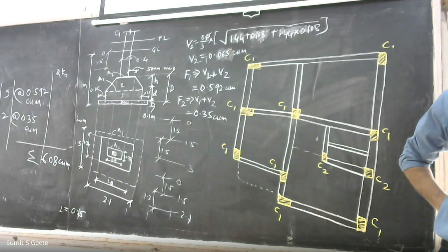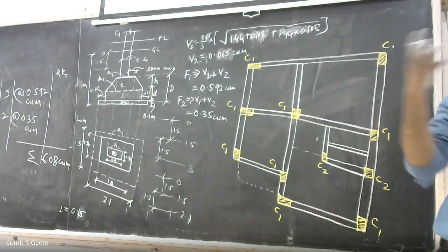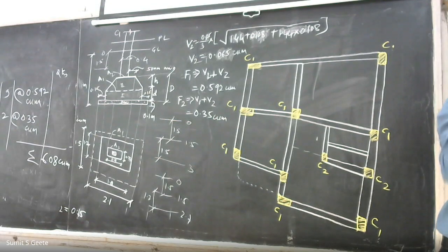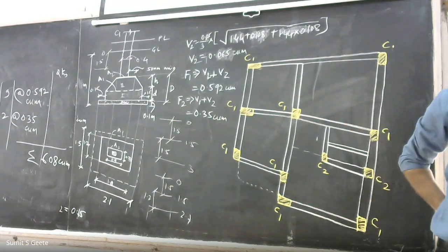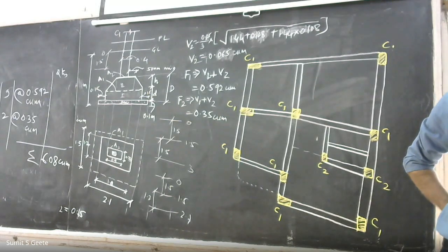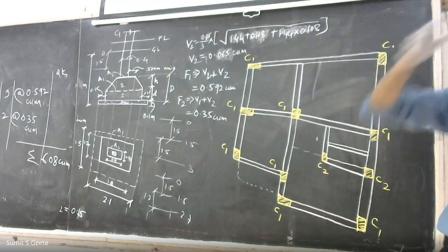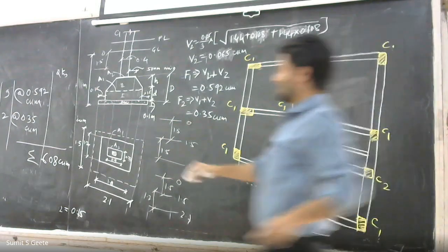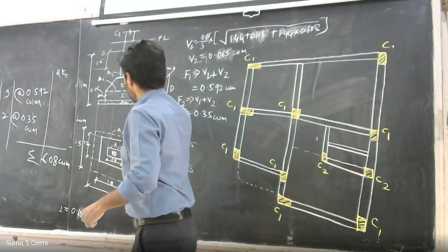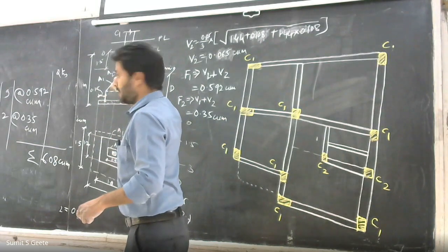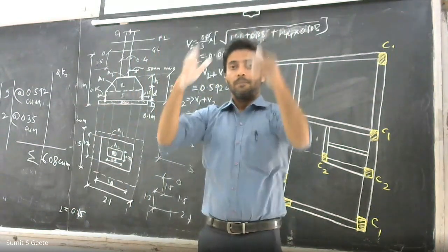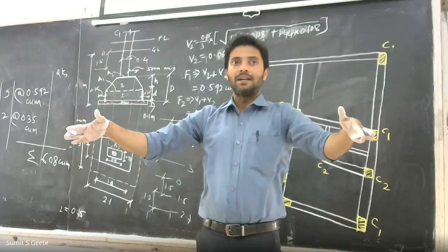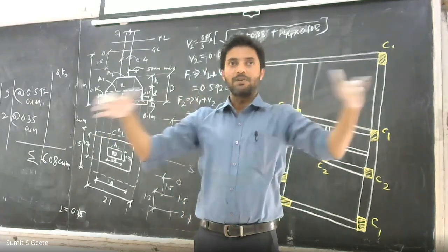It should be defined. If suppose you are getting a slump of say 30 mm or 20 mm and you want to do the concreting of the foundation, then whether it is possible to do. Secondly, how you are creating this trapezoidal shape, because you are just introducing the shuttering at this point only. You are not placing any kind of shuttering over here, so the mason has to define that particular shape. So how is that shape going to be defined?